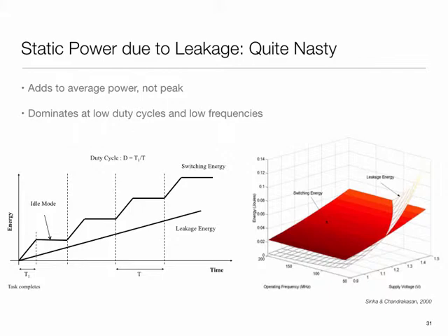Every time t, a new sensor sample or a new image comes in, so you have time t to process it. One approach is to occupy the entire time and set the frequency so that your finish time corresponds to t. The other possibility is that I run at a faster frequency and finish sooner, but then I idle. The third possibility is that I finish as soon as possible, but then power down the system, which would mean waking it up at the right time.